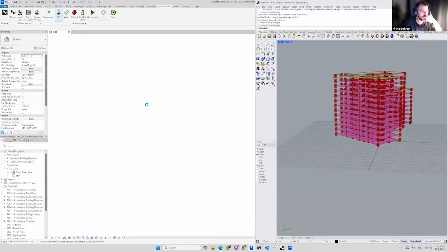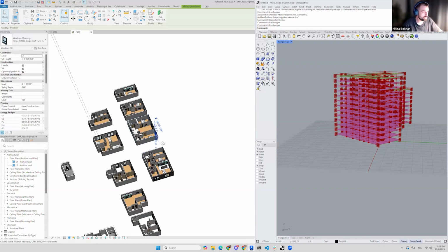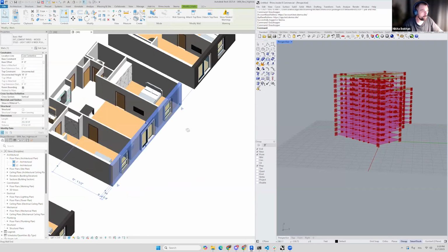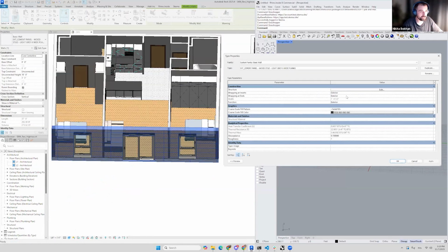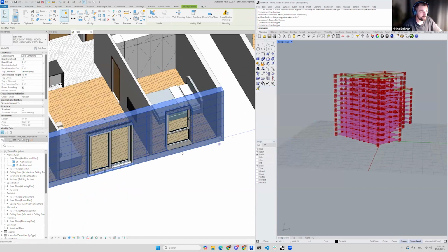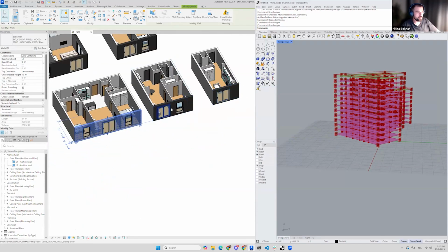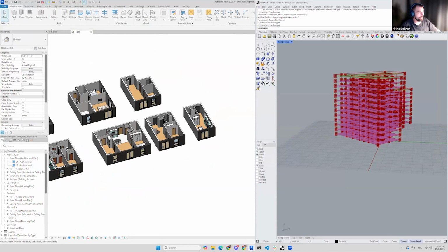But essentially, let's open my catalog file just to explain what is external unit wall and what is external general wall. When we upload our catalog, we have a type of wall which is marked as having an exterior property. For this wall, we use the type of wall which came from the catalog. If you have the same type of wall everywhere, we will generate this type of wall dictated by the catalog.